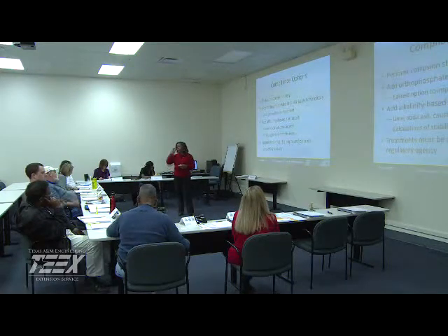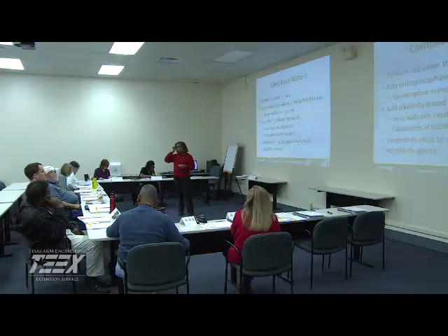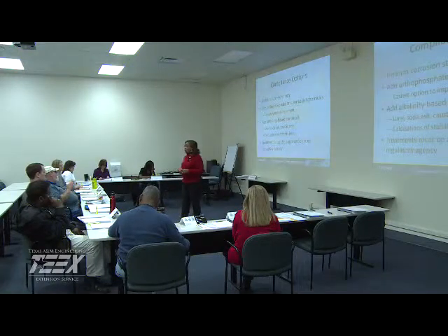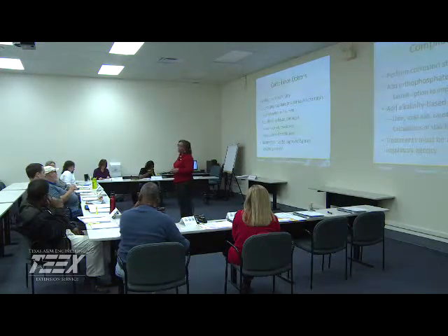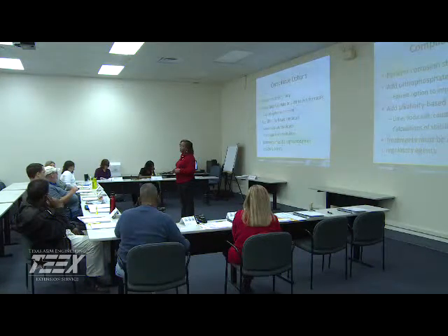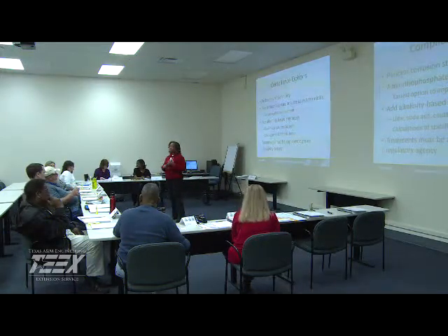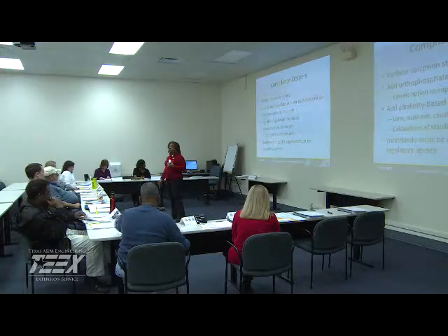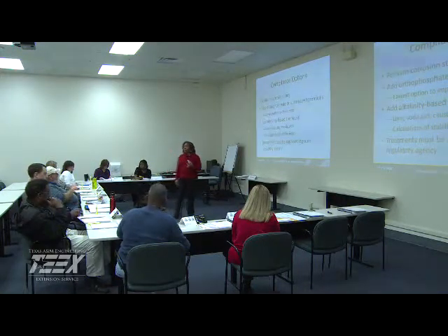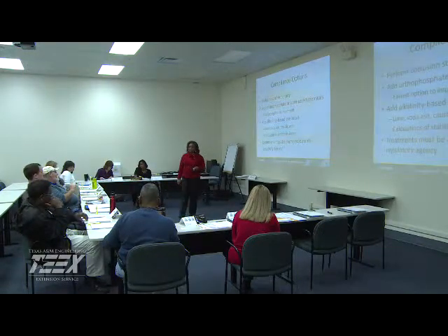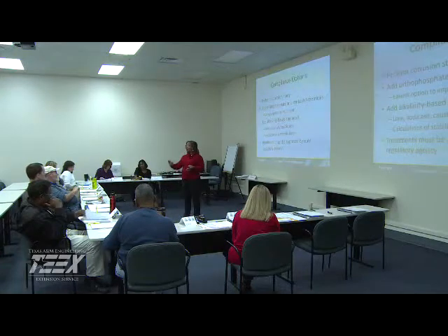So the orthophosphate is just protecting the water line from being attacked by the corrosive nature of the water, right? And it also sequesters. You're still going to be drinking it, but it's still on the line, it's protecting the line, see? So sequester is just keeping it where it's at, you're not really drinking it. So now we protected the property of our consumer. Yeah. And when you say sequester, it makes me think, well, it's still in the water you're drinking, if it's an iron issue and it's sequestered.